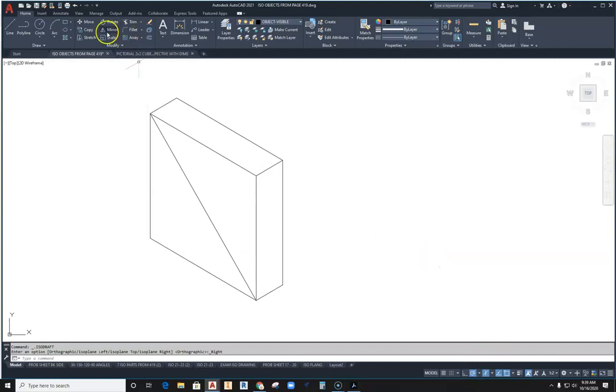Okay. So with that set, we pull down our ellipses. We hit axis end. Now we have the option for ISO circle. We click on ISO circle, and now it says ellipse specify center. Let's just click and pull and say, wow, that doesn't look right. So I'm going to hit F5. Yup, that's the correct plane, and this is the ISO left plane.